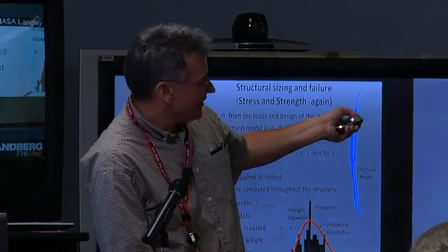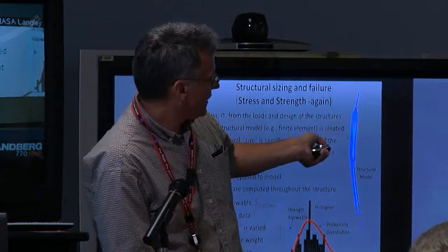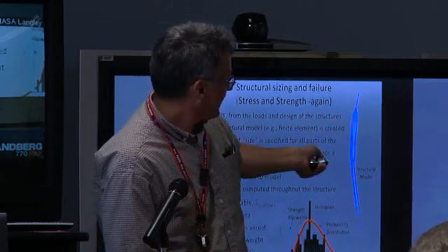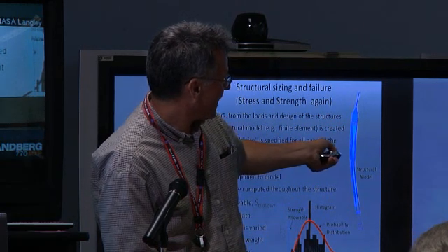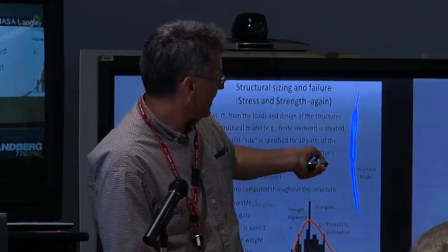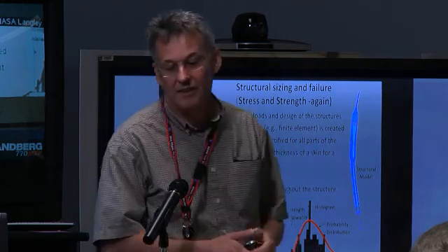And that's done by taking the structural model and the loads that are applied to it, and getting stresses. So based on the strength allowables we talked about earlier, we can get the structure size to minimize weight. What's the minimum weight without failure?